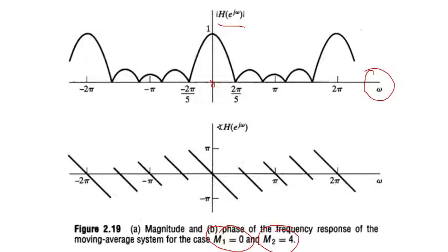Similarly for phase, I can choose different frequencies, and this is wrapped phase. I will tell you about the wrapped phase. Wrapped phase is always between pi and minus pi, because beyond this the phase becomes indistinguishable. So we keep the phase between minus pi and pi. All you need to do in the previous equation is find the equation of magnitude and the equation of phase, and then put in these values. I will give you this example to solve in MATLAB, because there you can compute it easily. So let's move on to the next slide.